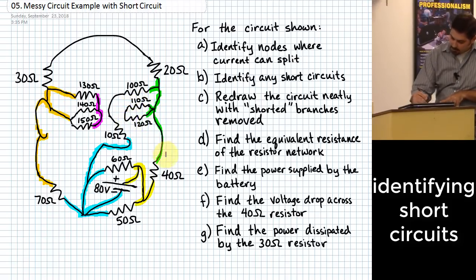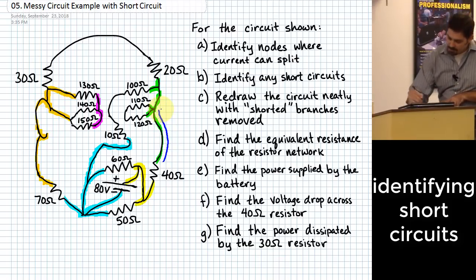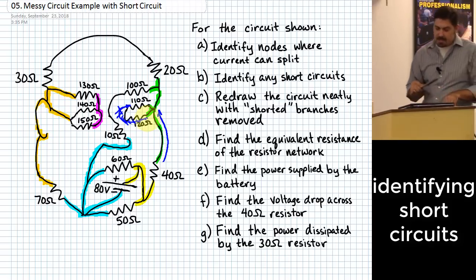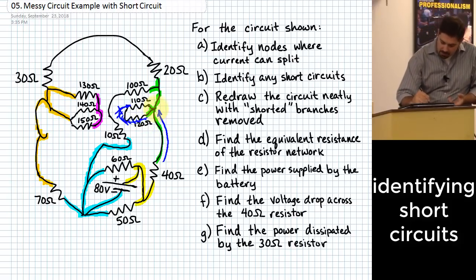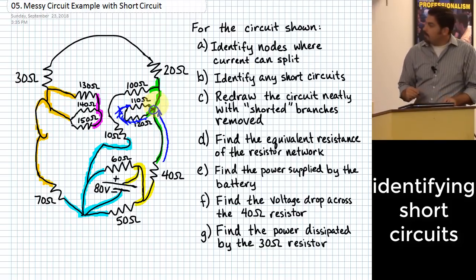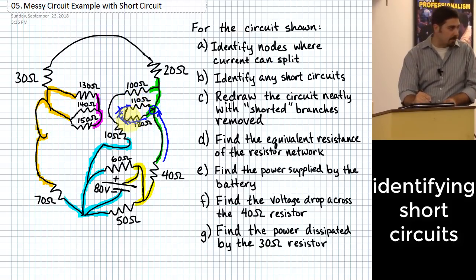As a matter of fact, there might be stuff that's pushing current like maybe along this way, perhaps, but as it goes through here, there's no reason the current would want to flow through the spectacles here, right? That won't happen. And the reason that won't happen is that there's a shorter path for it to go through. In other words, an easier path for it to flow through, because over here, right where it kind of touches the side of his head, right there is zero resistance. So all of the current's going to go through the spot where there's zero resistance rather than trying to go through this stuff where there is more than zero resistance. Does that make sense? Okay.